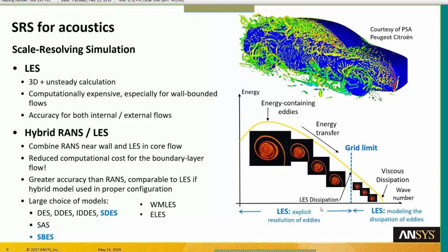But that is not what's happening in LES. In fact, we place the grid limit a bit above this limit, which is the Kolmogorov length scale. So when we place the grid limit for this LES calculation, it's usually at a fixed length for the grid sizing, and this size is usually not the Kolmogorov scale, but a little above the Kolmogorov scale.